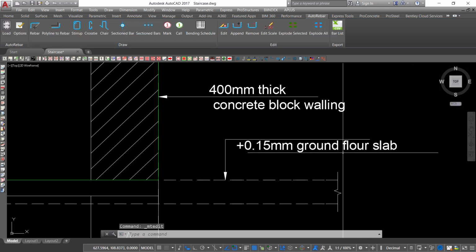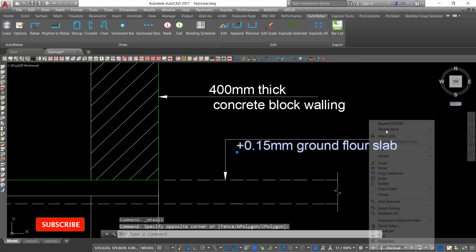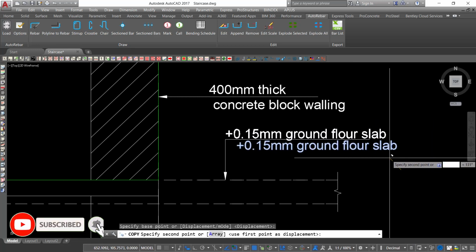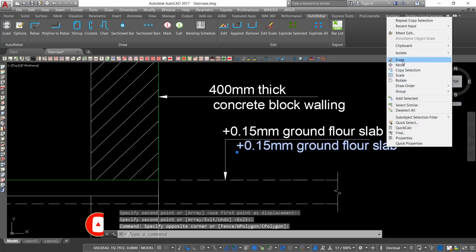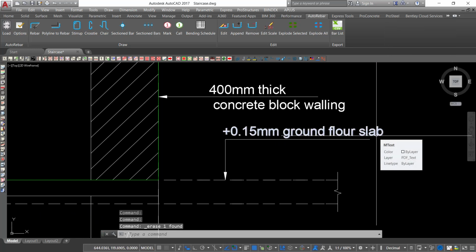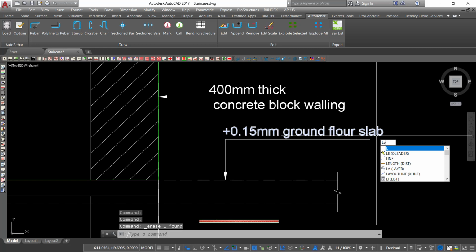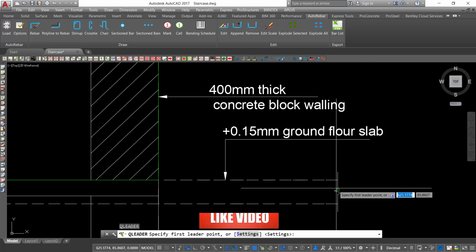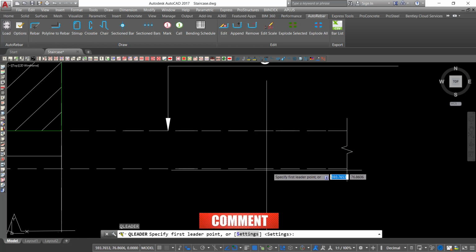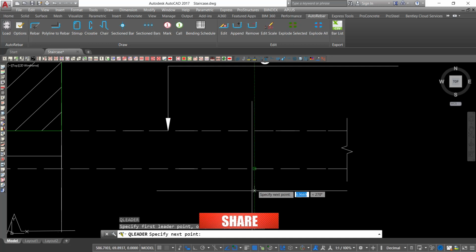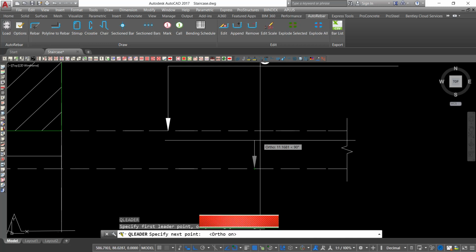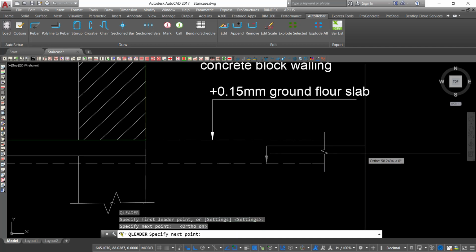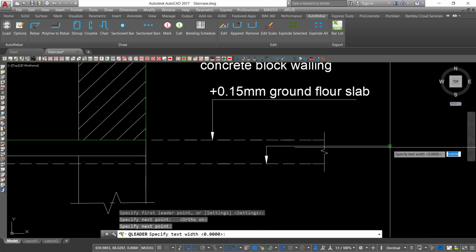Perfect. Just select it, drag it and place it on top of that. Delete this. The next is just type LE. LE is just a shortcut for leader, and we want to select on this, enable auto mode, and we'll terminate it from that spot and drag it all outward and terminate it right there.